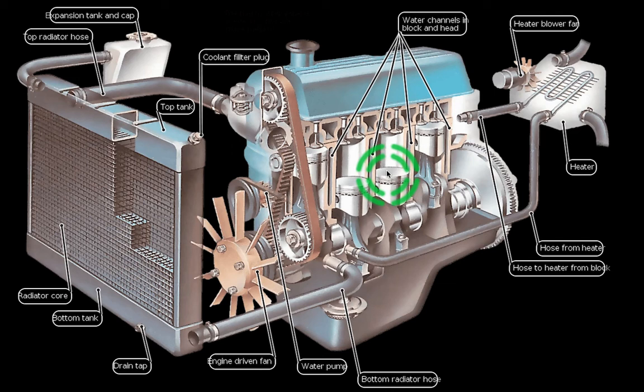Your air fuel mixture is not completely burnt. Sometimes it burns 100%, and at other cycles it burns like 50 percent. When you have this kind of variation, the engine will not be balanced, and that's why you feel that slight vibration. Although in modern engines you barely notice it, because there are so many compensations that take care of it. But yeah, that's what happens.